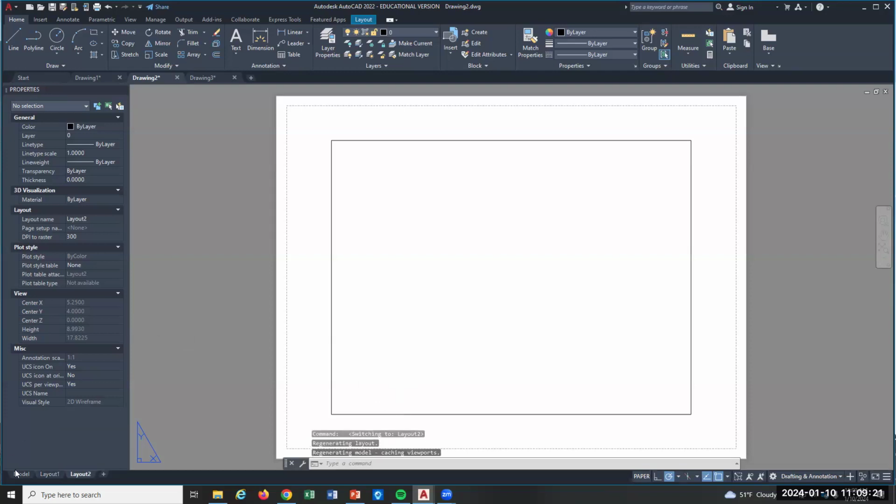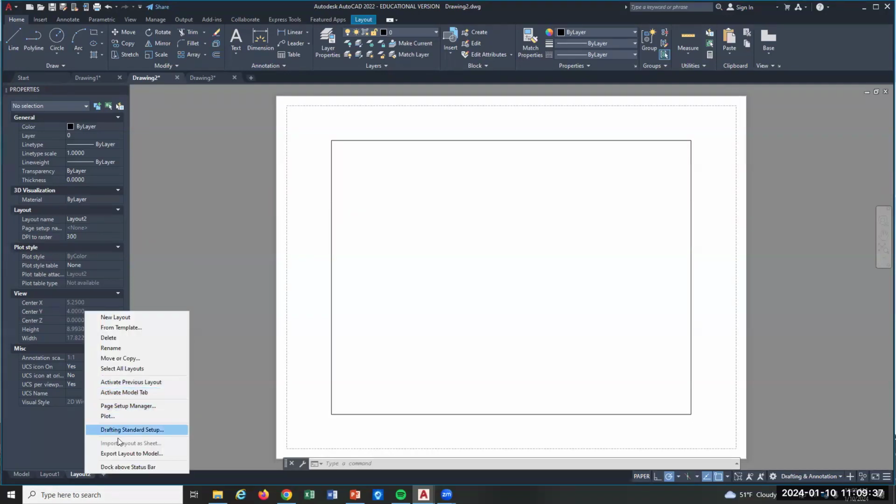And a B size layout. Well, they give you two layouts and they're both 8.5 by 11. That's what the ACAD template is, right? So to change that, you go down to layout and right click and you can open the page setup manager.